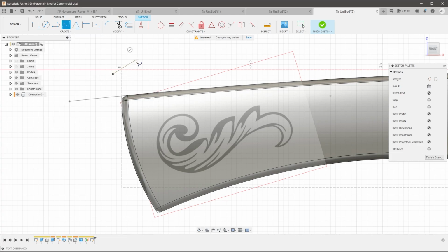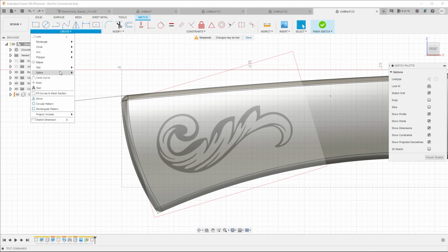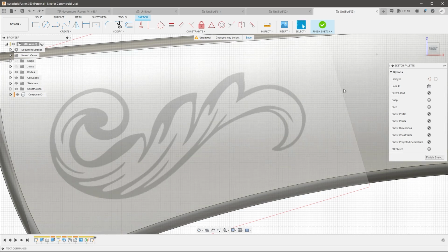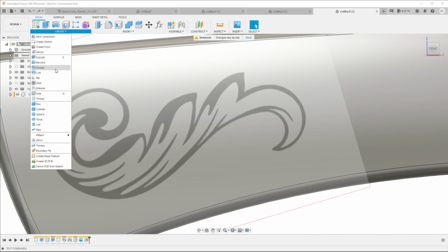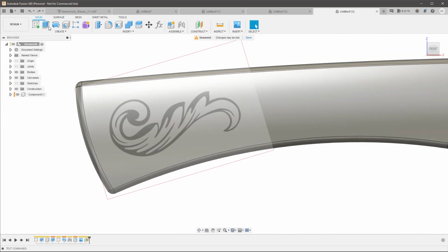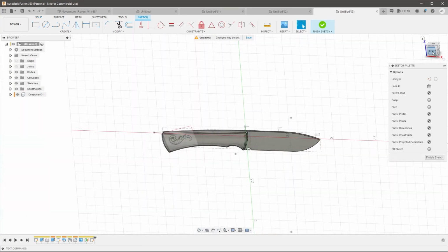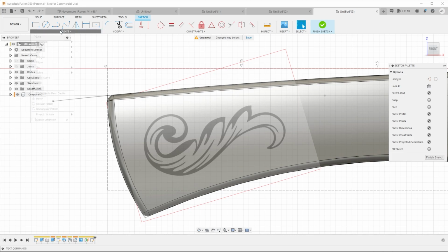A fit point spline, if you're not really aware, is you just drag points and it will start creating constant curvature between all of those points. And so that can be a really fast way to get a decent result. So like if I wanted to click here, then here, and keep going around that circle, it'll start to follow that circle pretty well, right? Oop, let me undo that. I accidentally lost it. Let's go back to sketch on that plane. Sorry about that. And let's do that again.